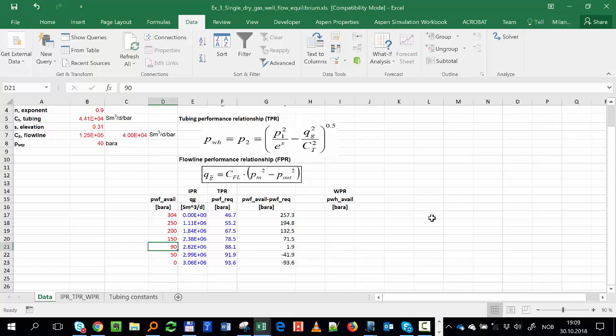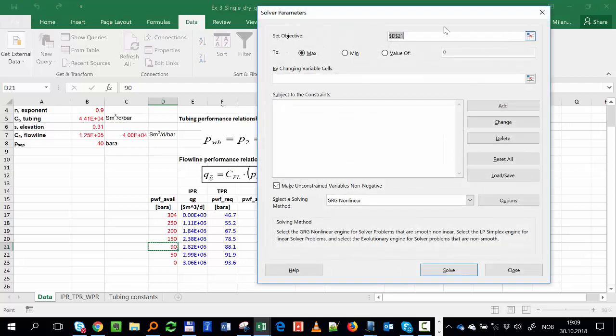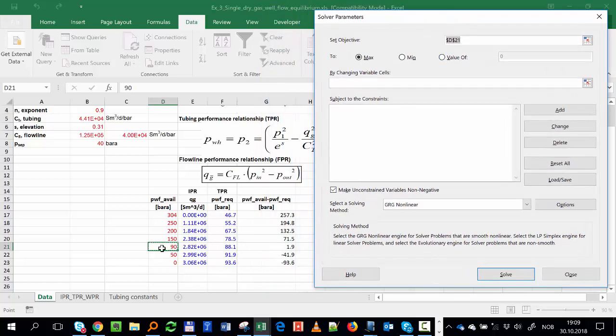Okay. Then we open the Solver. And the Solver says first, tell me what you want. So you say first, I want this cell. Okay, so we are going to use this cell. You could use any of the others, but I want to use a cell which, you know, I don't want the point to jump out of the curve. I want to continue the same trend as the rest of the curve. So that value, that cell, I want to drive to 0.